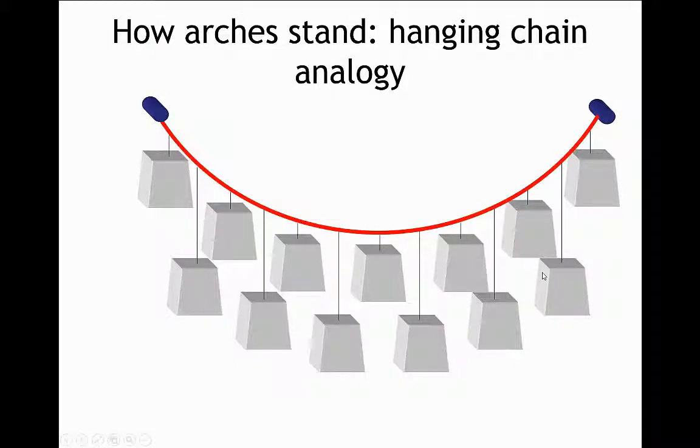So just going to a little bit of basic theory. How do arches stand? The nice bit of work done by Robert Hooke, probably close to half a millennium ago, goes something like this. As hangs a weightless chain, so but inverted, stands the masonry arch.